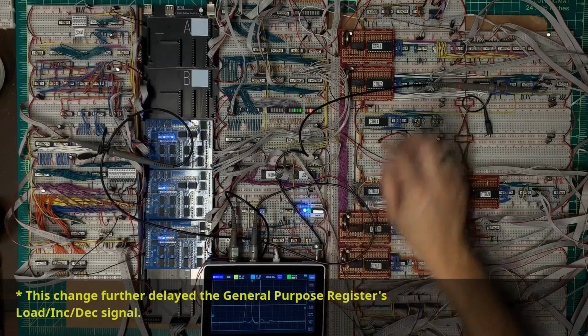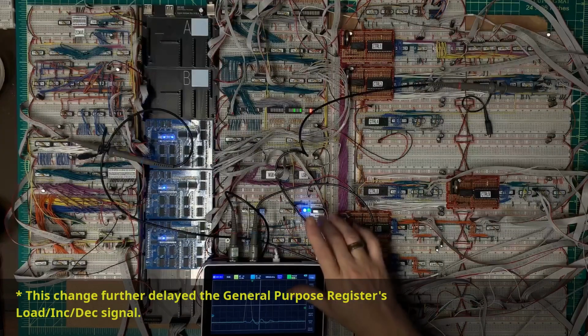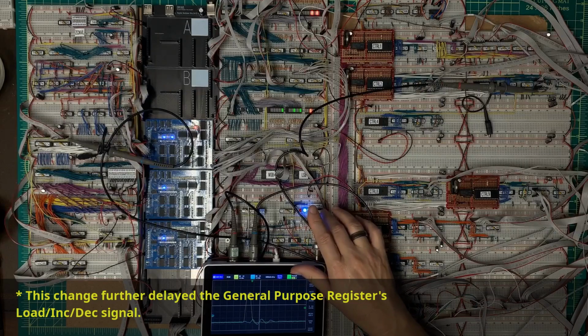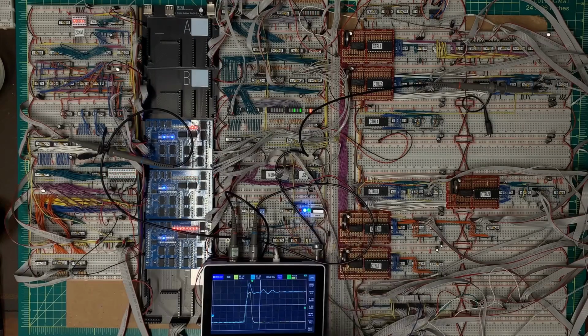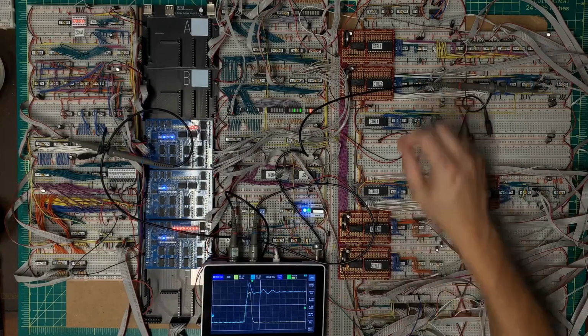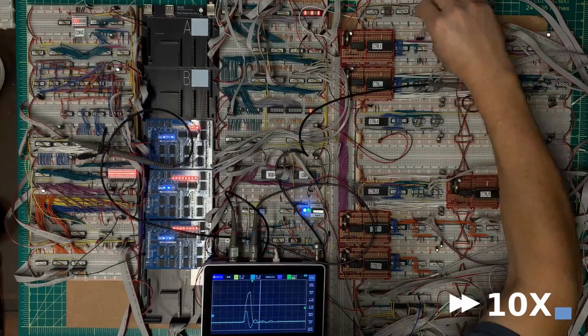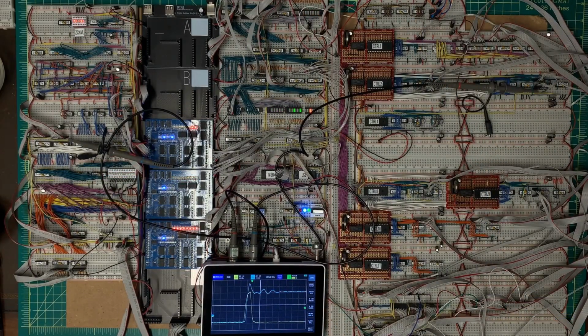Okay, let's see what that does. So I've now got 18 inverters in there, 19 if you include this one here. 19 inverters in there, trying to delay that signal enough. And that did not work. See if I can delay that latch a little bit more. So that has not changed the behavior nearly enough.